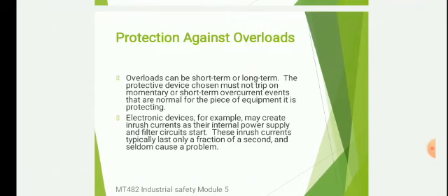We will discuss short term. The protective device chosen must not trip on momentary or short term current events. Electronic devices, for example, may create inrush currents as their internal power supply and filter circuits start. Whenever the circuit starts, whenever the internal power supply starts, it may create inrush currents. These inrush currents typically last only a fraction of a second and hardly cause any problem.